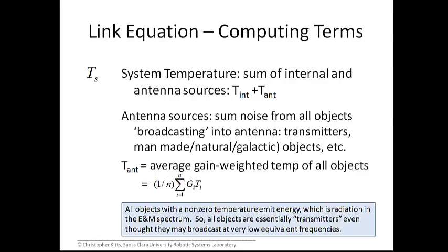So if I am on the Earth and I'm pointing the antenna toward the satellite and the satellite flies in front of the sun, then I'm going to have a significant noise figure to deal with, because the sun is putting out an ample amount of radio frequency, sort of microwave range energy. Conversely, if I'm on the satellite, antenna on the satellite, and the satellite's pointed to the Earth in order to communicate, well, the Earth is radiating as a black body, and it has a temperature. And so I would take that system temperature into account and go through this analysis.